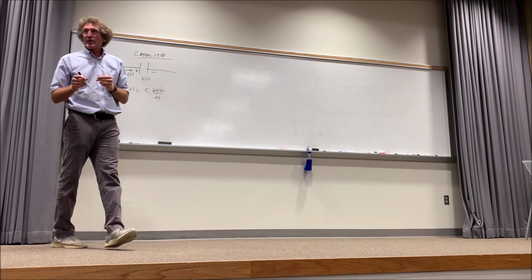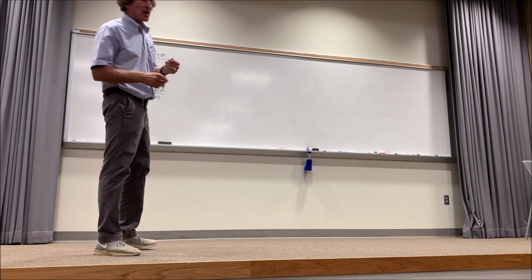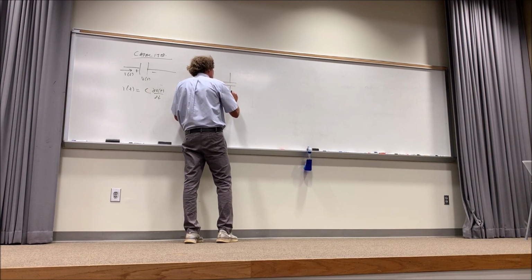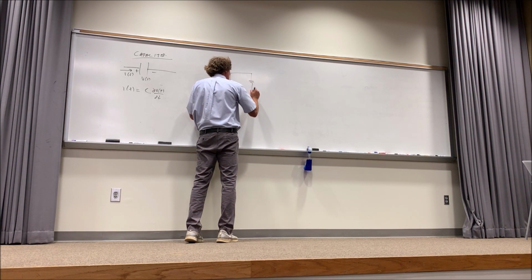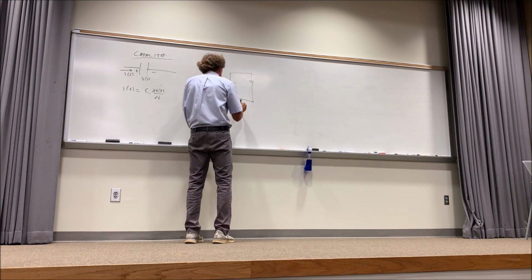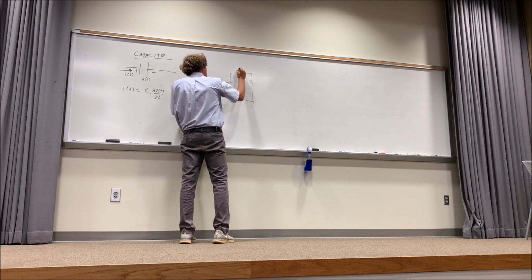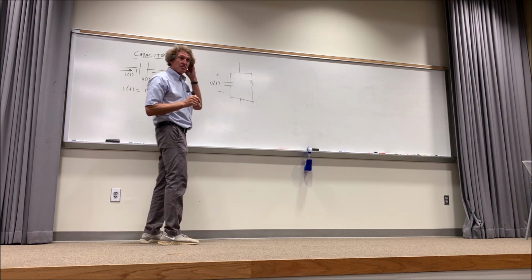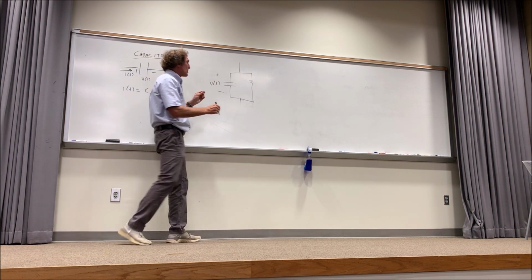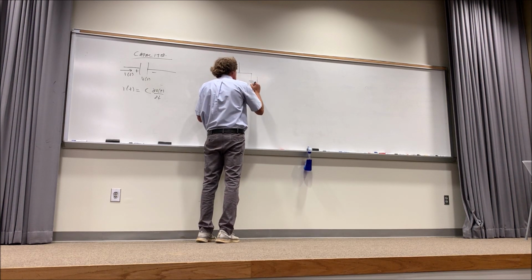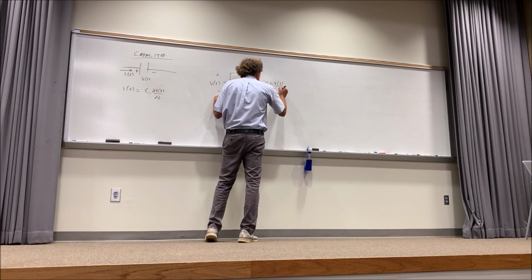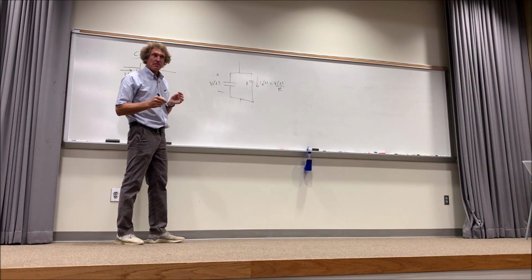Now, how do we go about solving circuits problems? For starters, we do this. We say if we have a capacitor here and a resistor here, and we have a voltage across these two, you all agree they're in parallel, right? Agree, class? If we look at that for a moment, I know if they're in parallel, the current here, if this is R, I_R of T will just be equal to V of T divided by R. You all agree with that?